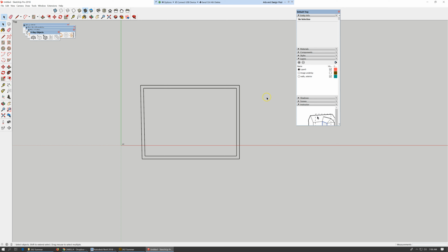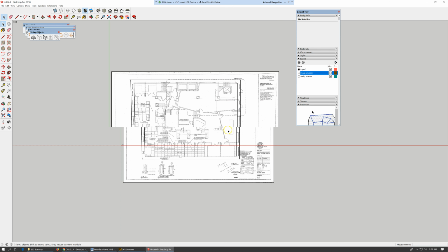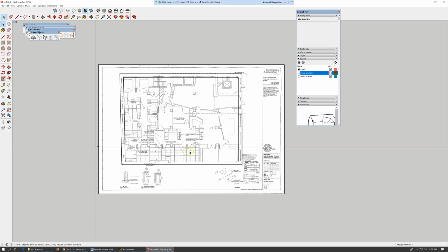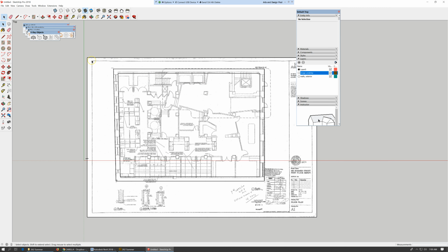There are other things that we need to document here. So the image is telling us what? There's a stairwell over there, there's stairs over here, there are what's in the middle of all this. There's some columns, right? There's a column grid. Let's go ahead and outline the columns, because we'll need to know that when we're doing our schematic design. So let's create a layer for columns.